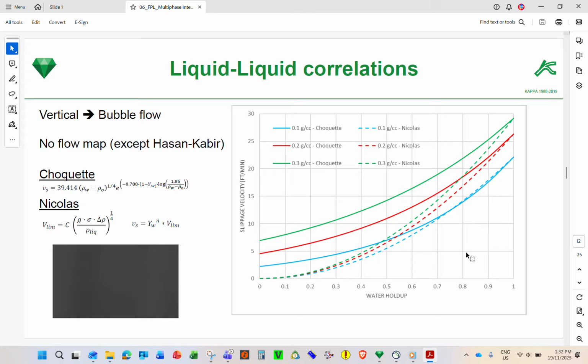So you can do that by just looking at these bubbles and the number of bubbles in maybe 1 second, and you calculate the gas rate. And that value is acceptable.